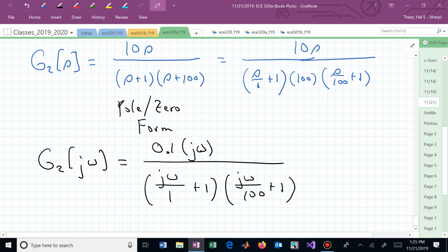One, you have to figure out what does he mean by small, and what is the phase at that frequency. What would you think small represents? Is it an absolute number? Oh, anything less than 1. That was maybe a poor choice of numbers in the beginning example. Anything less than 1 is small. No, because you might have a transfer function that's doing all of its activity at poles and zeros, 0.001, 0.02, etc. Very small.